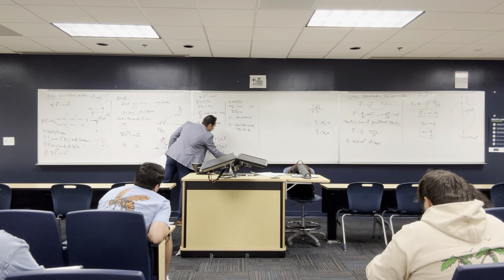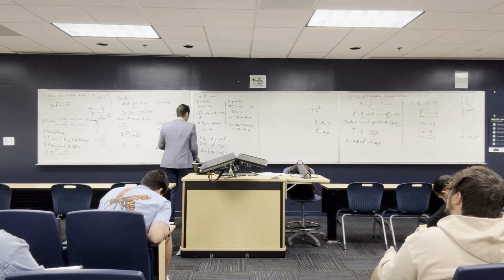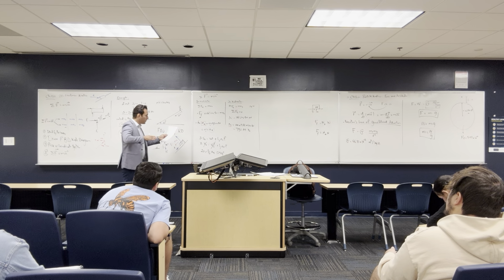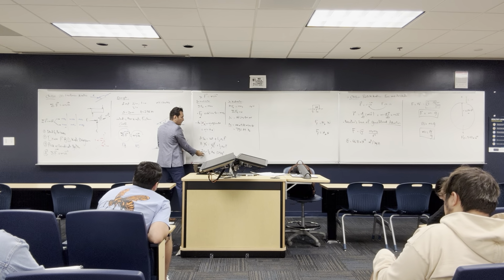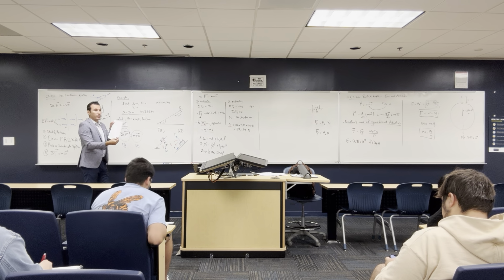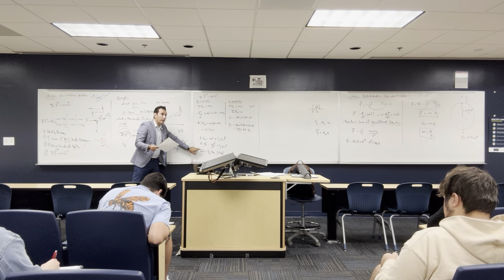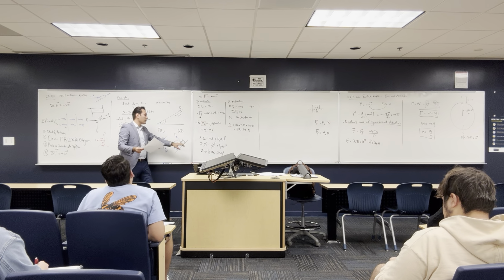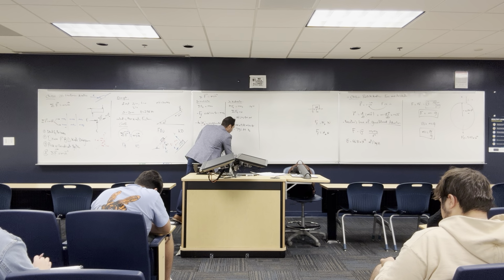So this is going to give you that a_x is equal to... by the way, this is not going to be negative because here I assumed the x direction is going up, and here I assume the x direction is going down. So if you calculate this, the 20 is going down. By the way, so that you can understand what I did here, I put x going up, so I put the distance as negative 20. Right now I put x in the same direction as the distance, so I put it here positive. So this value is going to be 6.09 meters per second squared, and it's positive.